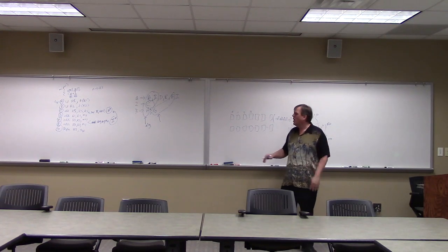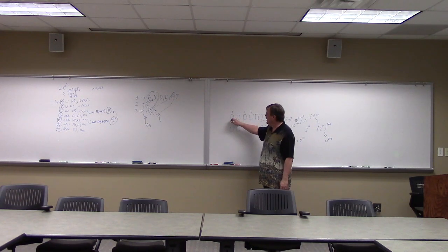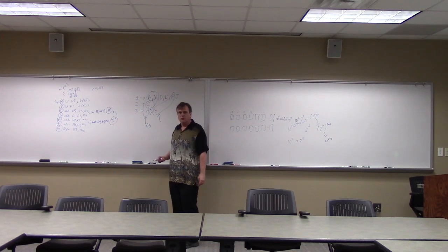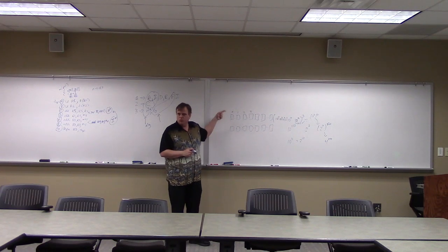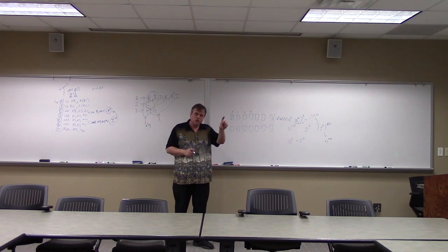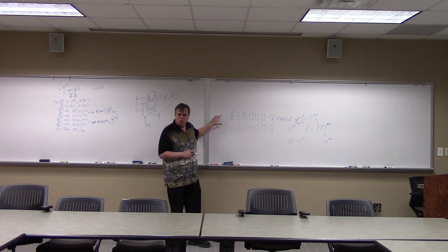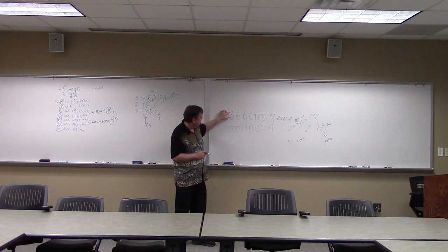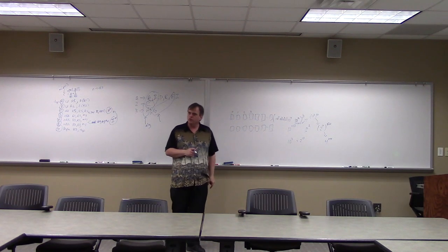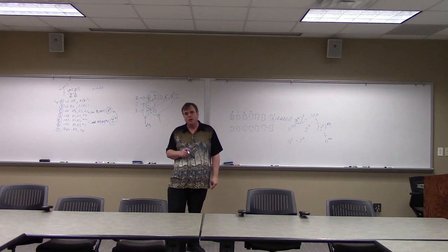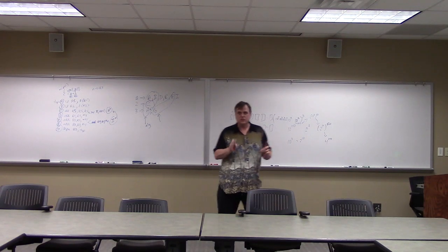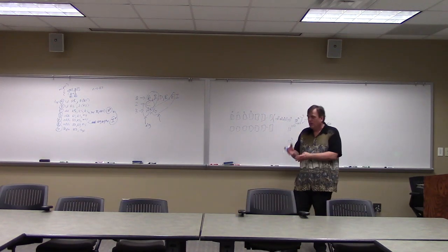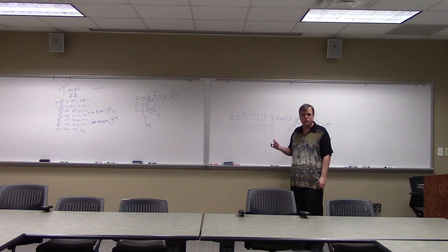Inside here, each of these has a data stream. Why do I need to reload that stream? I can take a window, and we've already talked about these for instruction buffers. I take a window, I get it ordered well so it's nice and efficient, and I don't need to reload anything, I just need to get the data. So your memory accesses just went down. You're data limited; the only memory problem you have here is data, but as long as I do really wide data on this, I'm good.